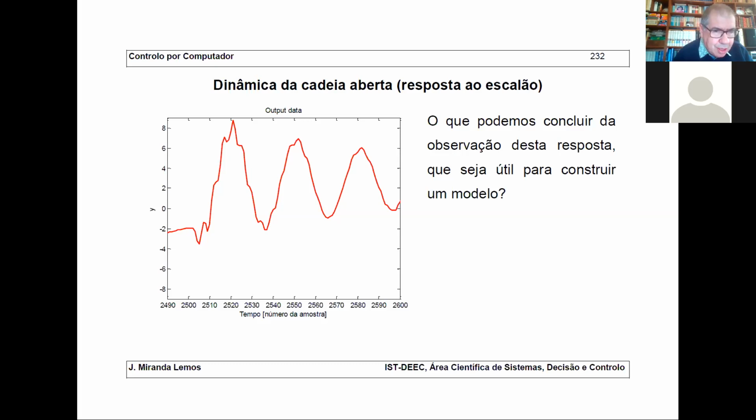We have a non-minimum phase zero because we have the valley in the beginning. I apply the positive stimulus and it goes down before going up. Physically, we can understand this. You understand why? Yeah, I guess so. It's like it's contradicting the effect of the input.